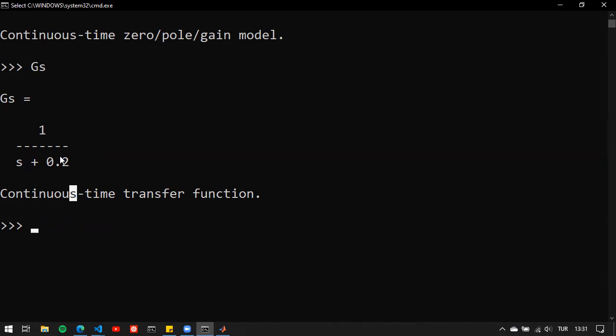Because if we have a PI controller, we would not decide on the position of the zero. It will naturally arise. Therefore, maybe it would not be suitable for dominant pole placement. So therefore, using a PI-PD controller is somewhat between designing a PI controller, getting the benefits of that, and a PID controller.